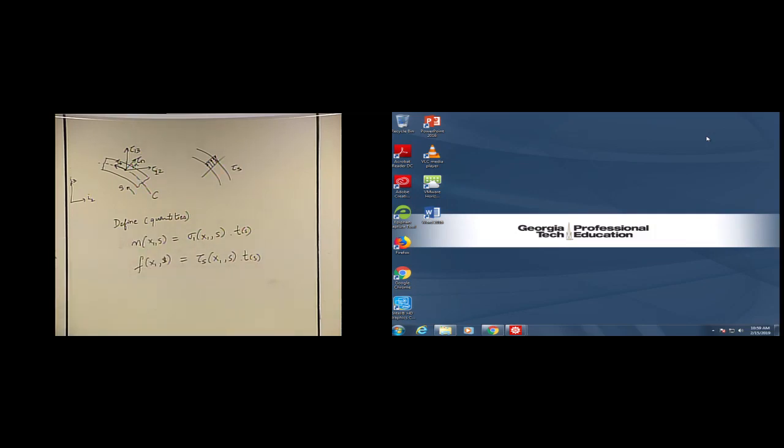So in thin wall beams, because the shear stress is generally constant along the thickness, a shear flow is studied. You just multiply the thickness with the shear stress and you get shear flow, and that's the quantity we study for thin wall beams for designing purposes or for calculating shear centers. You must be familiar with this from your undergrad classes as well.